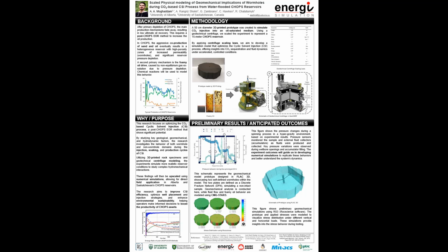Today, I will be presenting my research on scaled physical modeling of geomechanical implications of wormholes during the CO2-based CSI process from water-flooded CHOPS reservoirs. This research focuses on optimizing the CO2-based cyclic solvent injection CSI process for enhancing oil recovery from cold heavy oil production with sand reservoirs, or CHOPS. It addresses the geomechanical impacts of wormholes, a key feature in these reservoirs, and provides insights into improving the efficiency of this enhanced oil recovery method.